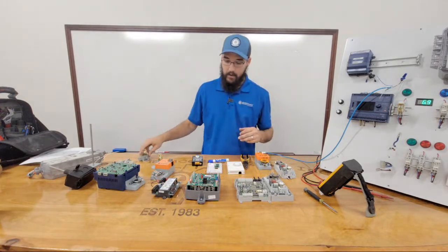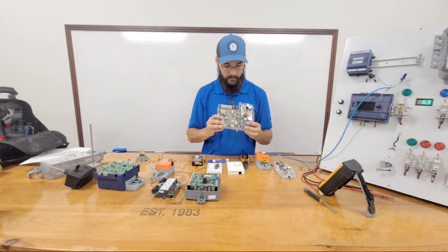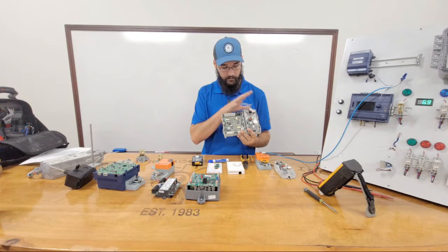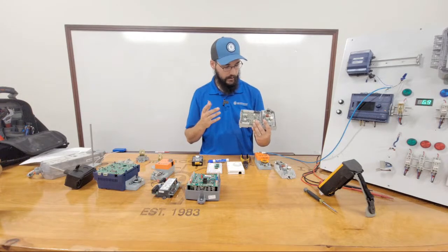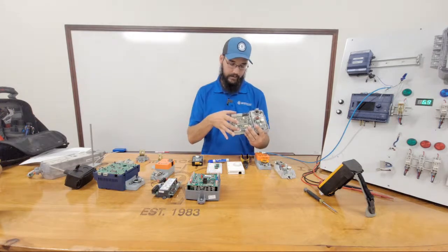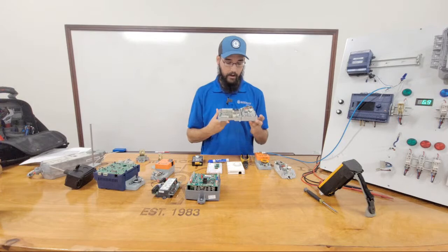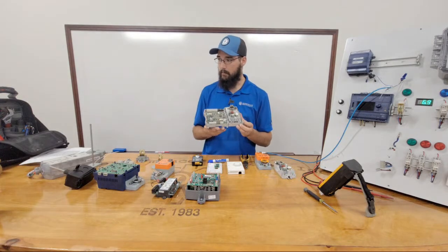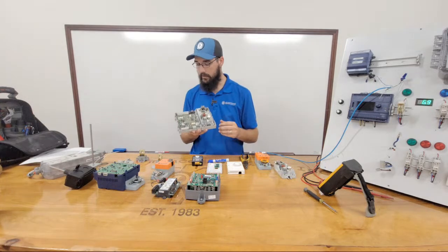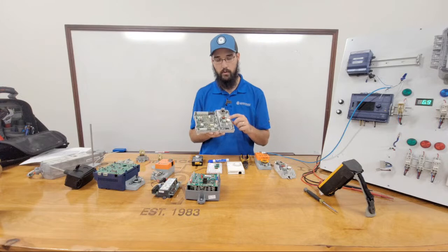Moving on to give you just a basic rundown of a typical controller. So this is a Honeywell. This should be a Spider series, where you've got the main control module and then you've got the actuator attached. Now, this would be something you would put in like a VAV box or a fan power box, and the vast majority of the time, these are going to be a floating point style control.